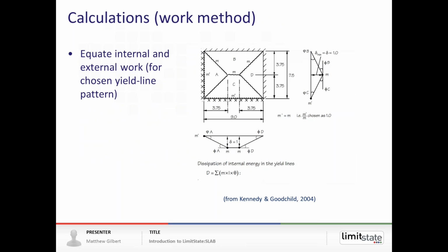So what does that actually mean in practice? Well, it means that we can analyze the capacity or provide a prediction of the strength of a slab relatively easily using hand calculations, at least if the geometry is simple. What we typically do is guess a mechanism, we then deform that mechanism, and then we would typically equate internal work done by the yield lines to external work done by the loads.